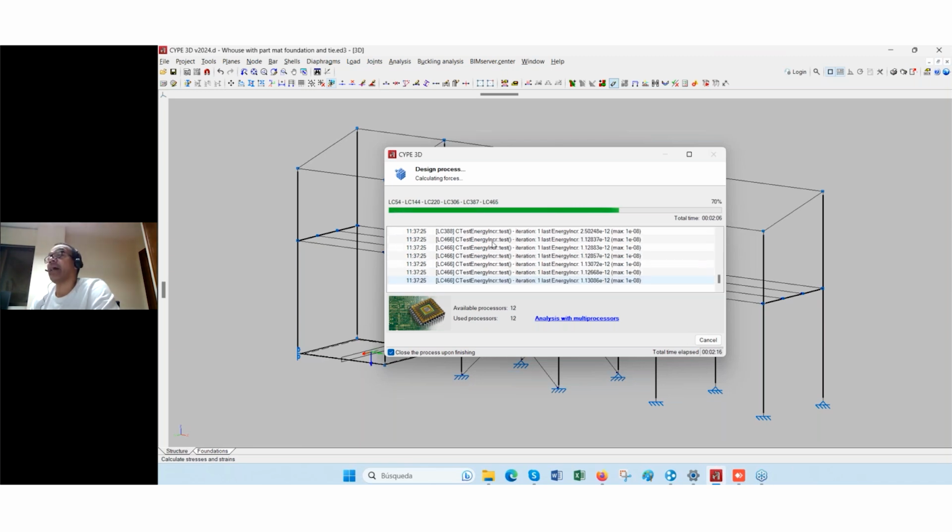If you have a tie, which is a bar, where we have only tensile behavior, you just set it. You don't have to do much. If you are worried because you have to create combinations, you don't have to. The program will make the nonlinear combinations the first time you run the job, simply based on the linear combinations.